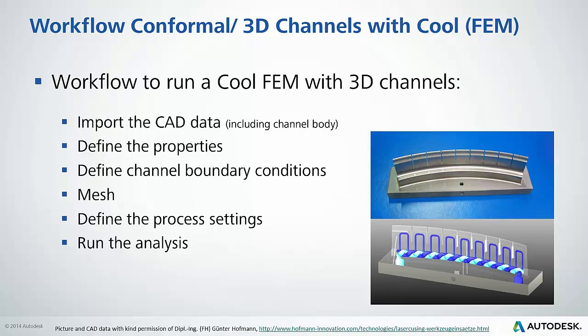Well, now it's a little bit different. We've got to bring in a CAD body to represent this shape. And that's what we're kind of seeing down here highlighted in the blue through this core. So we need to define the properties, and we want to do this at the CAD body level. We need to call it a 3D channel. And boundary conditions are actually set on the CAD body, and that's a little bit different than what we're used to doing. It's a CFD thing, so we'll see that.